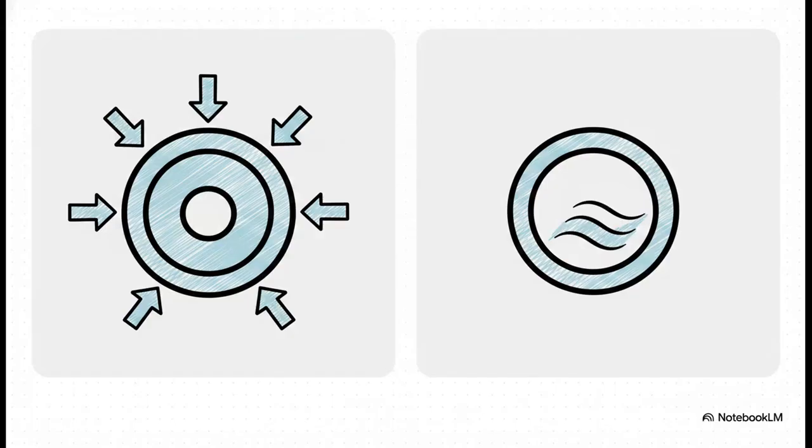This perfectly illustrates a core engineering principle. Increasing the schedule literally just means increasing the wall thickness of the pipe to handle much more extreme internal pressures. But, and this is key, the outside diameter is completely untouched. Why does that matter? So it always fits perfectly into standard external connections and supports. A higher schedule gives you a thicker, stronger wall with less space inside, while a lower schedule gives you a thinner wall and more room for standard flow. It's basically a perfect balancing act between strength and volume.